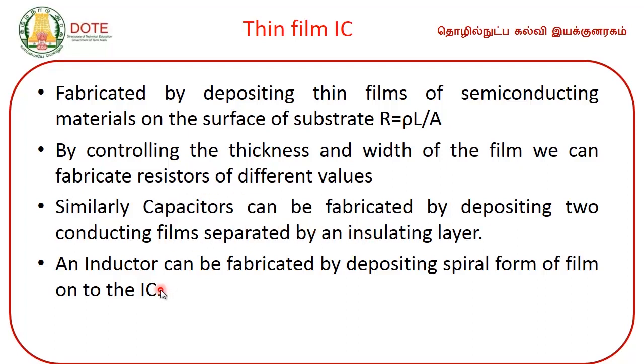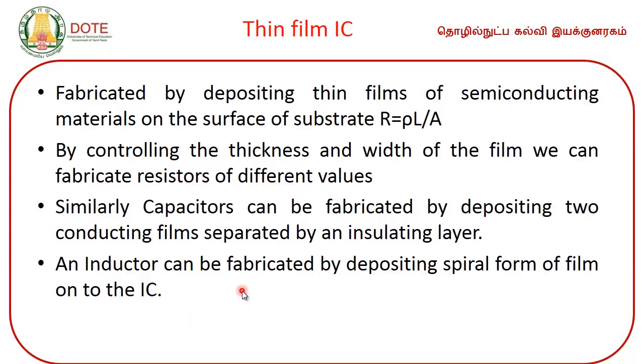What about inductor? Is it possible to fabricate inductor using thin film technology? Yes. On a substrate, film material is taken in the form of film and it is laid on the material in the spiral form, right, similar to the coil. That way you could fabricate thin film inductors.